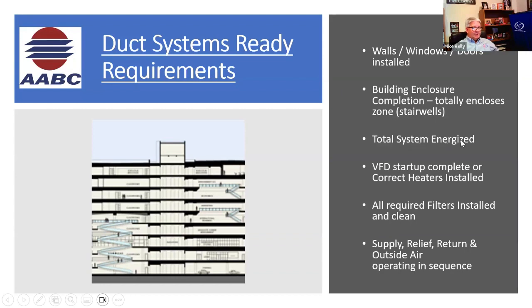Total system energized, meaning everything's energized. We're not running off of, well, we have the supply fan running, but the return fan's not ready yet. Can't balance it. I mean, you can, but it's not going to be accurate. You're fooling yourself to think this is going to be a great total system balance at the end.